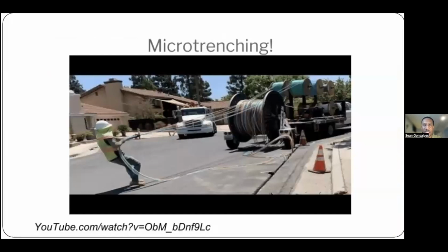Now, there's something that is a little less expensive and a little less cumbersome than digging trenches, which is something that they call micro trenching, which is a fairly new way of deploying fiber underground. As opposed to it being several feet underground, we're talking about maybe several inches underground, and typically they'll cut a strand in the road, as you can see in this picture, and lay the fiber in there. Now, again, this is a sort of new thing, and I've heard mixed results on these things that I think have a lot to do with weather conditions. In places that are particularly cold, microtrenching may not be such a great idea. Also, by the way, Departments of Public Works don't really like it when you're ripping up their roads, especially because it reduces the lifespan of that road. So there are those considerations as it relates to micro trenching.